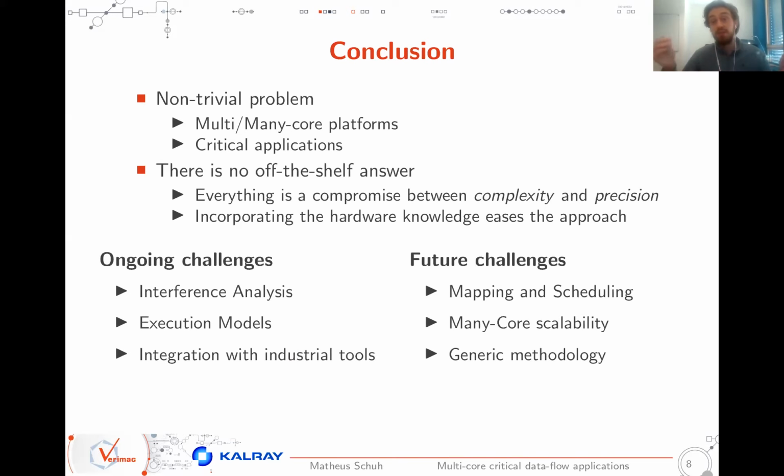So the system engineer can only design the program in the SCADE suite platform and target it to the MPPA3, and all the code generation and the global response time calculation will be done automatically, improving a lot the development time it takes to actually deploy the solution on the MPPA3.